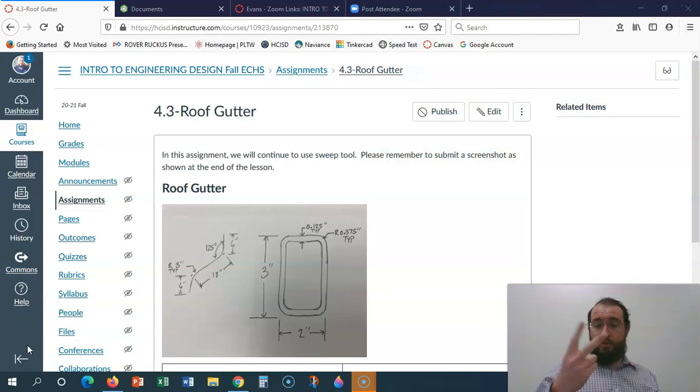So it's going to take two sketches. If you remember before, we have a path sketch, which we're going to draw first, and then we have a profile sketch. Now, I drew the path sketch way smaller than it is. So we're going to make these two sketches and then sweep the part down. So you might want to have these numbers written down if you haven't started already, and pause the video, write them down, and then join me over in Onshape.